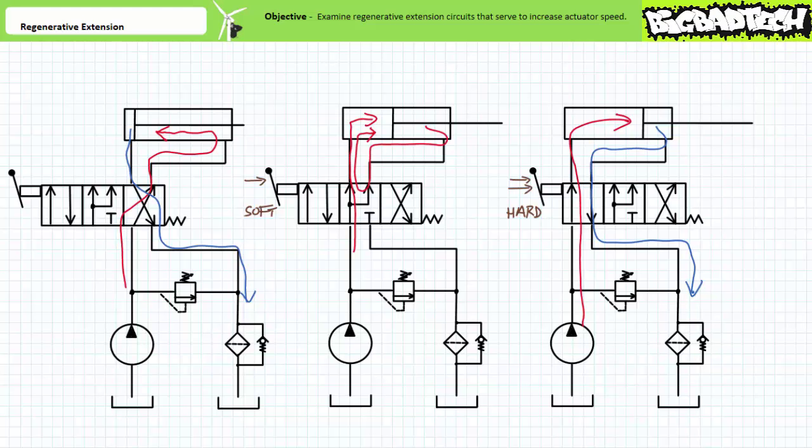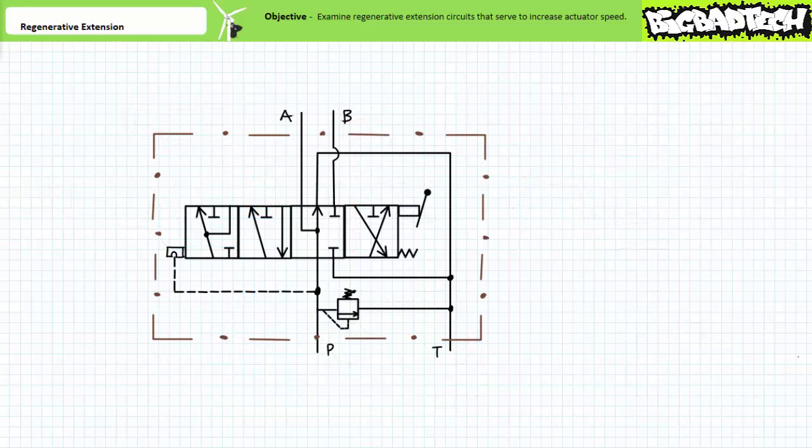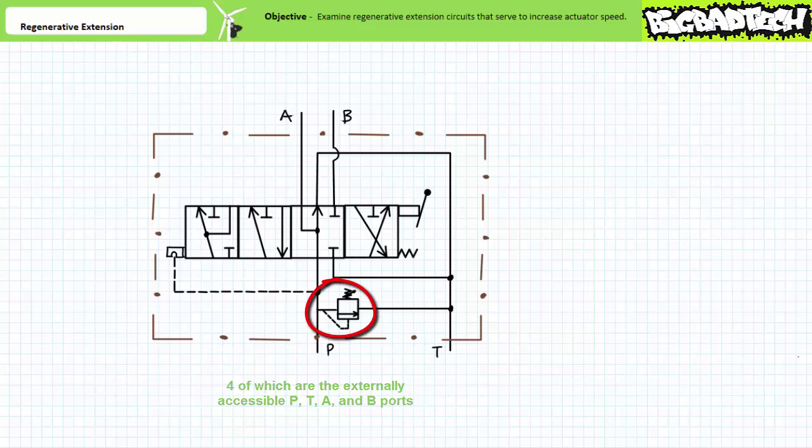Absolutely full. Here's yet another directional control valve with regenerative possibilities. The schematic symbol is a little busy, but if you take your time, you should be able to figure out what is going on. First, this is obviously a manually actuated valve. It has 4 positions and features a mechanical detent. Internally, it has 5 ways. Note the enclosure symbol also includes an integrated pressure relief valve.